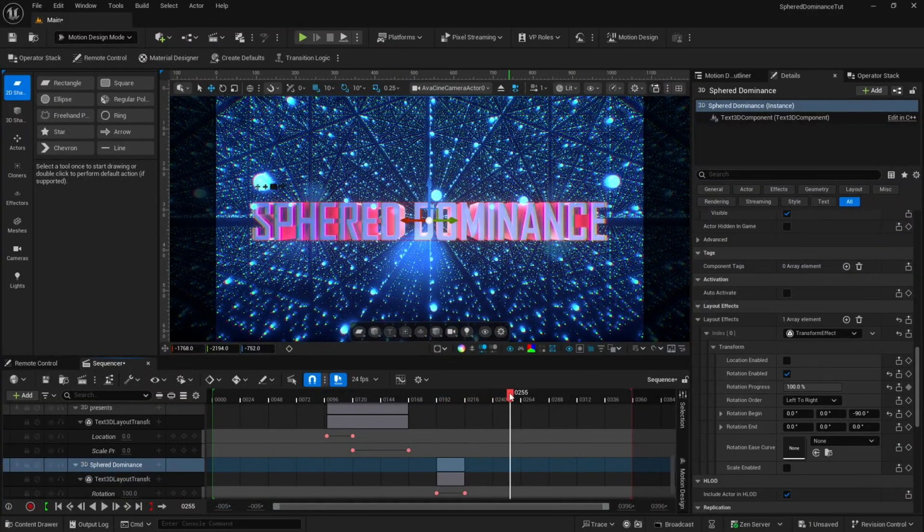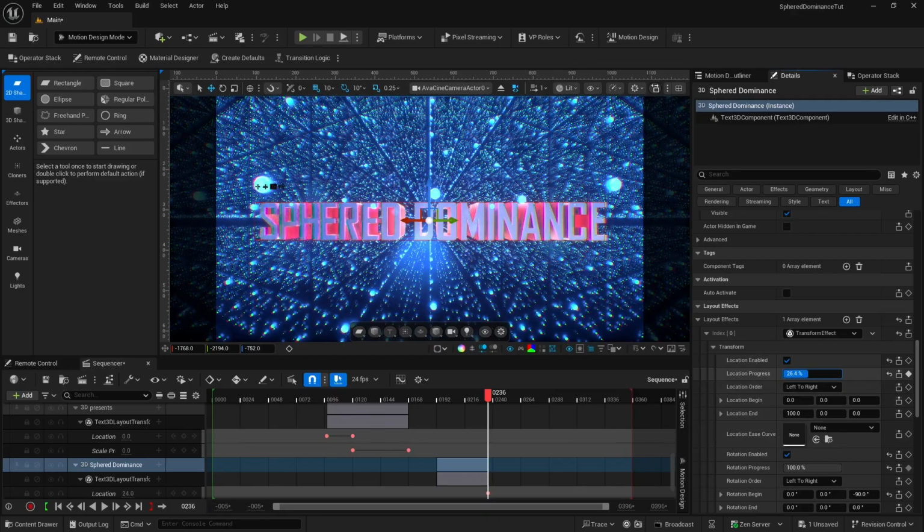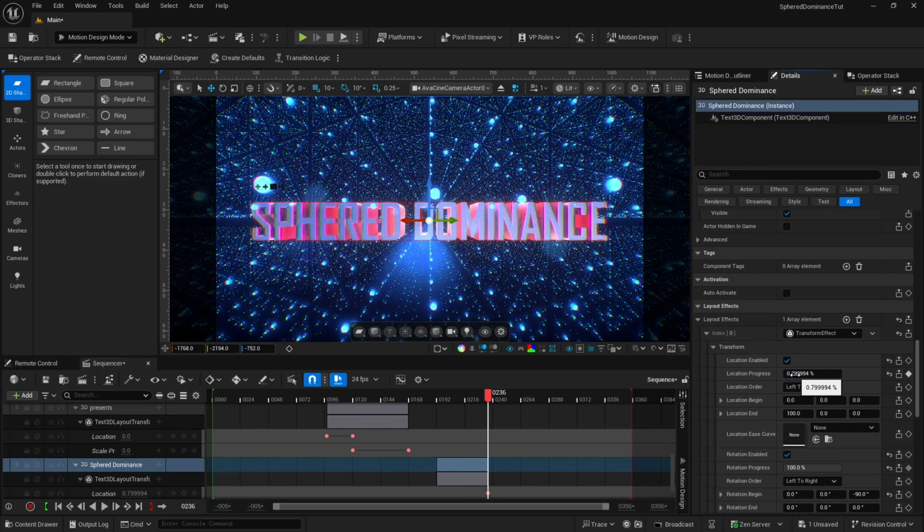And then to animate this text out, I'm going to go to 236 in the timeline. And I'm going to enable the location. And we'll start the animation right there. So we're going to set a keyframe for that location progress right there. And we will need to change the location end because right now the way that it's going to animate, you'll see that it's going to go backwards away from us. And I actually want this to go forward.